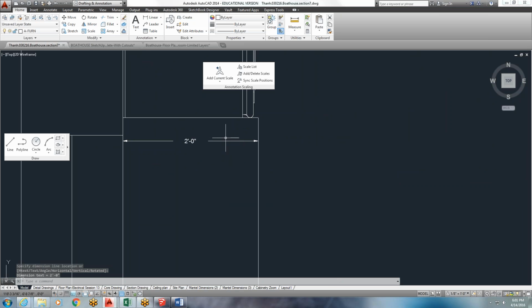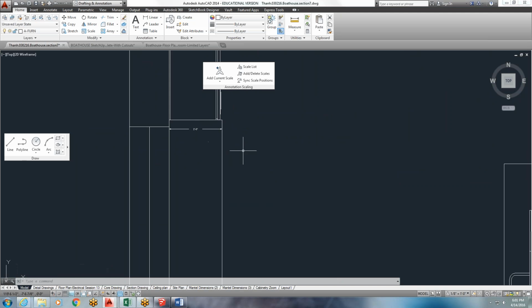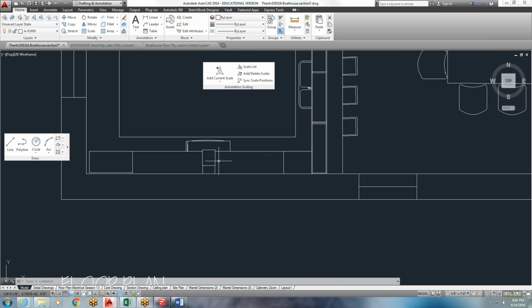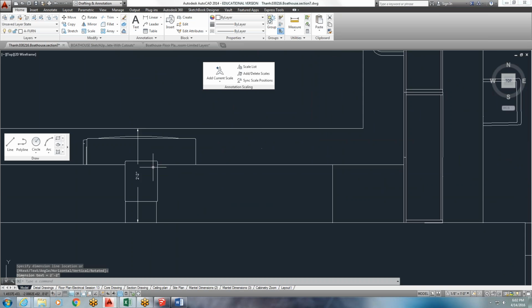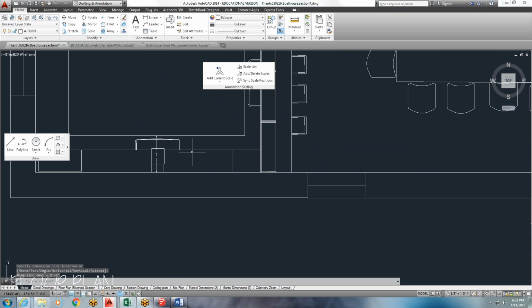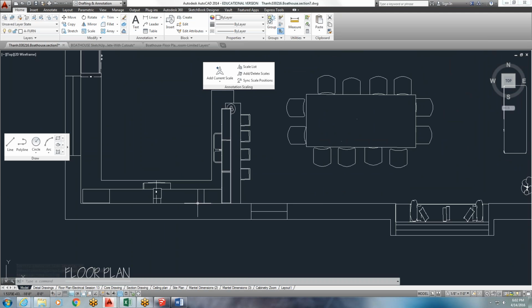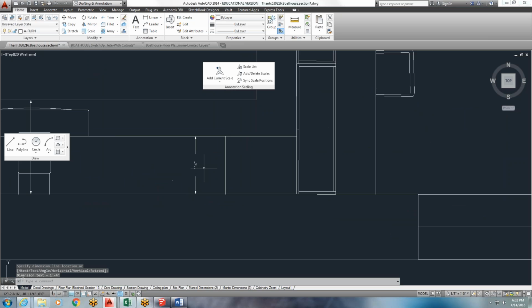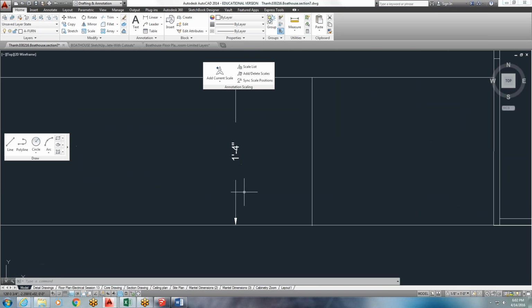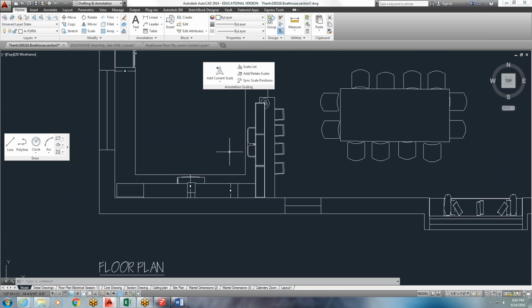24 inches is actually pretty accurate for the base cabinet. We'll just need an overhang for our countertop. And let's see down here how far we're off on these cabinets. 2'2", so we'll need to come in an inch so that we have the overhang for our countertop and space for our base cabinets. Our upper cabinets should be about 12. They can vary to about up to 15 depth, but that's very strange for European style cabinets. Usually it is about 12 or 13, taking into account the door. So this is quite large. We'll have to adjust that.